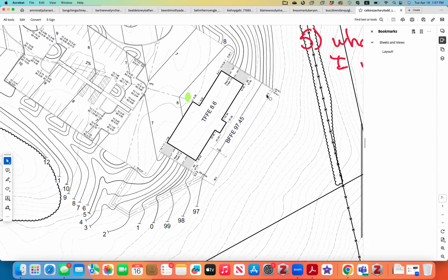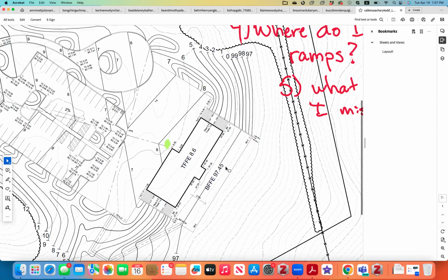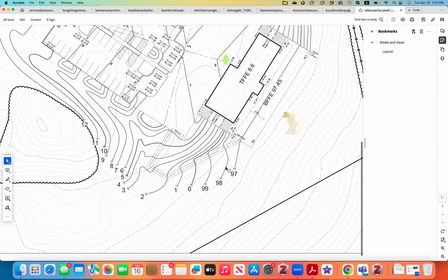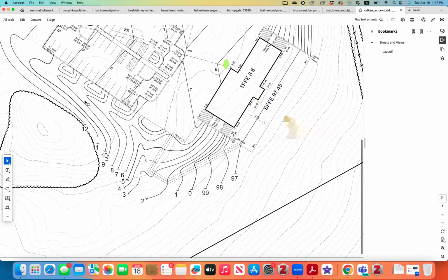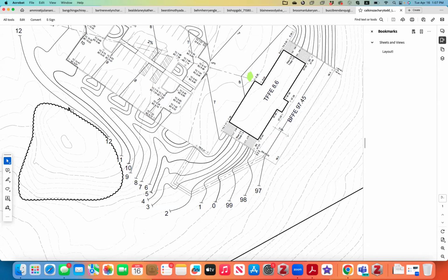Yeah, these contours look like they will be working fine here. I would polish, no, we're missing a contour here of 13. We need to close the 13. So it's likely that everything here needs to shift 4 feet in that direction because this is the 13.